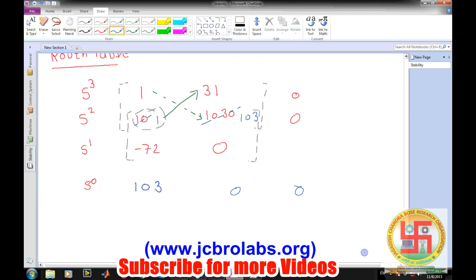Now let's have a look to understand how this Routh table works. We just check the sign of this first column. Remember, we are interested only in the signs of this first column. So this sign is positive, then positive, then negative, and then positive. Now rule 1 says how to find whether this system is stable or unstable.